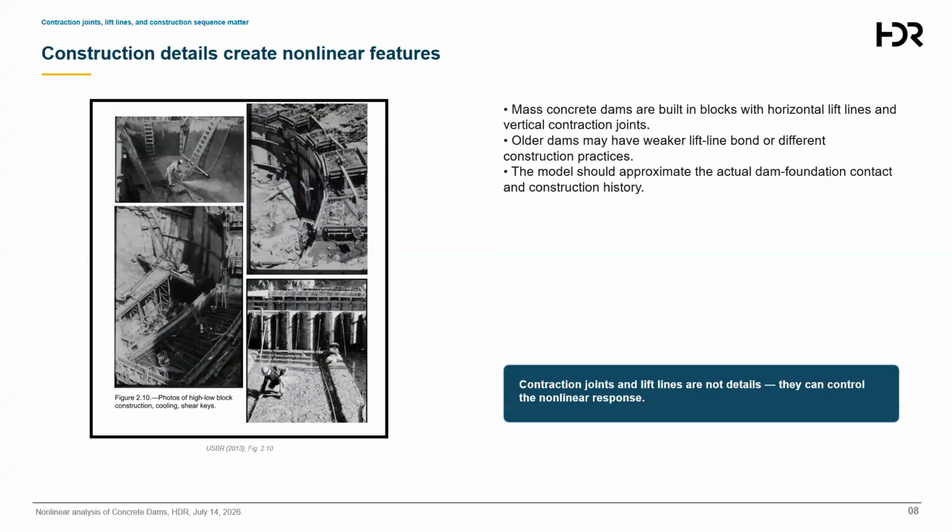Mass concrete dams are built in blocks, vertical blocks actually, and horizontal lift lines. So these surfaces can be potential planes for opening, sliding, or stress redistribution. So in nonlinear analysis, the model should reflect the actual dam foundation contact, lift lines, and contraction joints as much as practical.